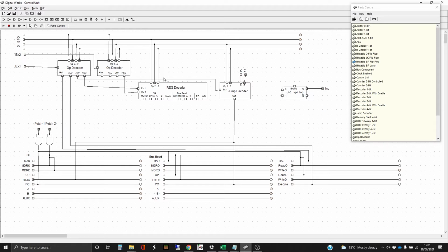And what we're going to do is make this reset, so go to 0, when we jump. But then at the beginning of every cycle round, we're going to set this back to 1. And we'll do that as part of fetch 1. So where's fetch 1 here? Tracing which of these lines? Is that one? Is this one here? And we're going to stick that into the set.